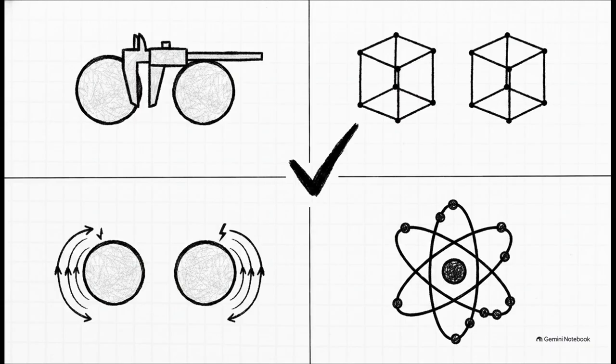For them to form a nice, stable, substitutional solid solution, they have to play by a strict set of guidelines known as the Hume-Rothery rules. First off, the two atoms must have a size difference of less than 15%. Otherwise, the crystal just gets way too distorted. Second, they need to naturally form the exact same crystal structure. Third, they should have similar electronegativities, because if one is way more electronegative, they'll just react and form a compound instead of a mixed solution. And finally, a metal is much more likely to dissolve another metal if it has a higher valency. When these rules align perfectly, like with copper and nickel, they can mix seamlessly in literally any proportion.